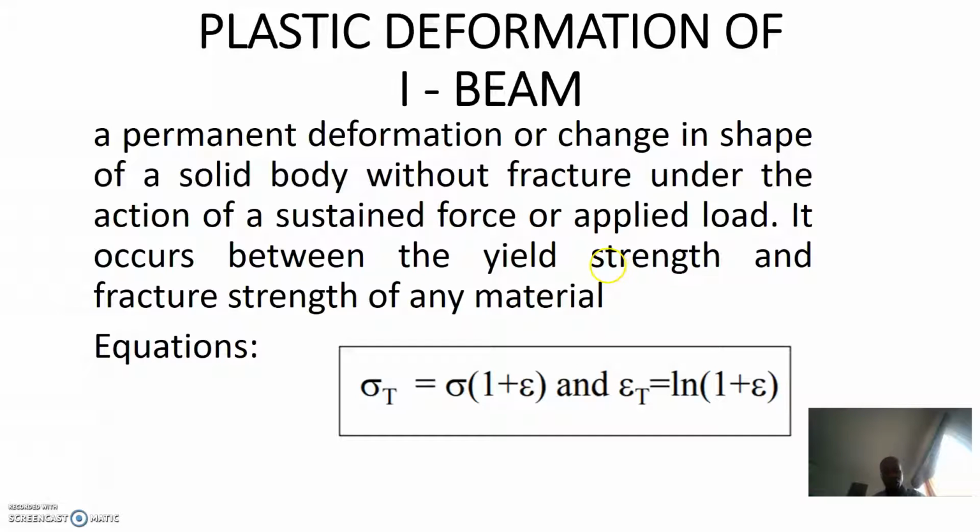That's why we need to keep our load below the yield strength of the material that we are using. This is the equation of the plastic deformation. This is the plastic stress, and this is the plastic strain equation. And this equation will govern our analysis in ANSYS.